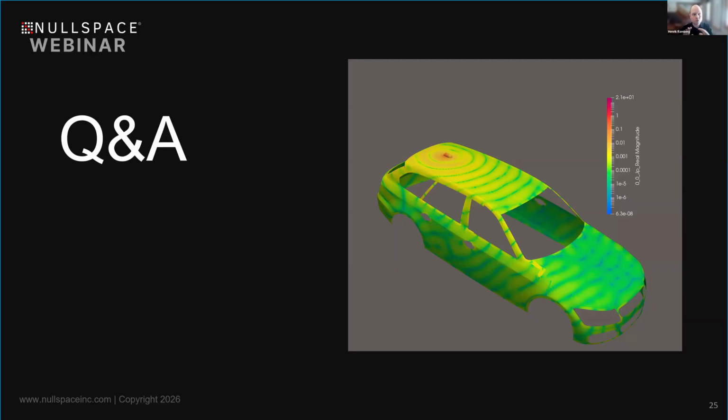As we tried to explain during the webinar, that is a good thing, because maybe it seems a little difficult in the beginning, but with very straightforward guidelines, as you start playing with it, you will learn a lot more about your antenna and where to put the denser mesh, and you will always be in full control. And you always try it out on a smaller model before you do a phased array.